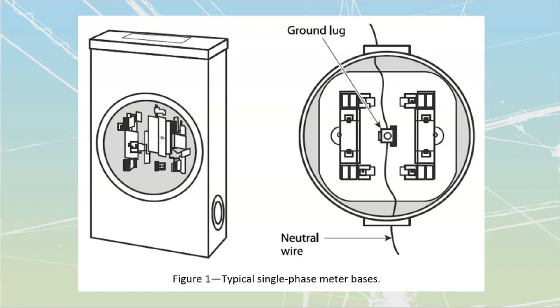So you could have a building, feasibly, that is a 120-240 single phase. It's also got a 120-208 three-phase to it. It's also got a 277-480 three-phase to it, and a 347-600. I don't know why you would ever want to do that. Instead of dealing with all that paperwork and Hydro, you'd be far better off doing it all yourself through transformers inside there, but it would be allowable.